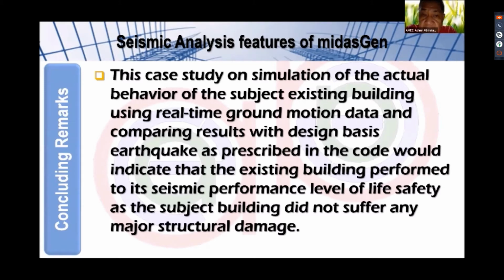Actually, we inspected this building right after the April 22, 2019 earthquake, and we haven't seen a single structural member manifesting or indicating cracks that seem to be progressing. The damage that we have observed is on the ground floor, which affects only the non-structural walls, which are the concrete hollow block walls.